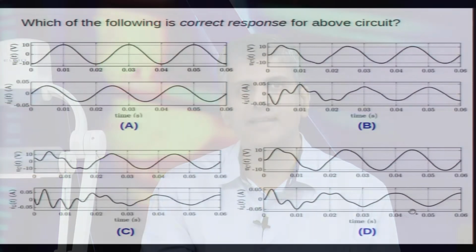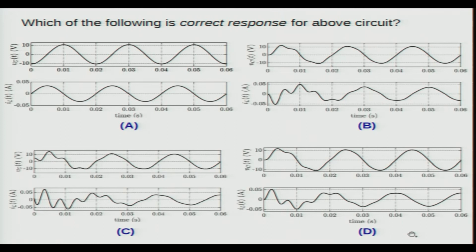There are a few takeaways here. There is a distinction between a natural response and a steady state response. The natural response will display properties of the roots of what is known as the characteristic equation. In this case it was S square LC plus SCR plus 1 is equal to 0.